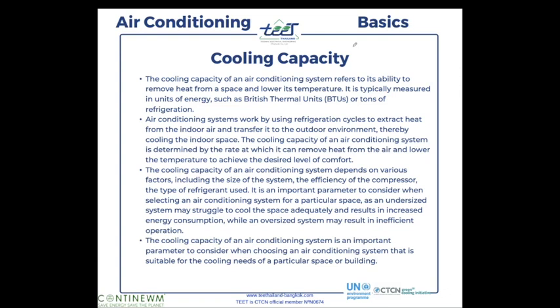But this would be only a guidance. What I am afraid of is that just because it's written on a slide, it's always working. No, we have to always look around. Let's take a supermarket with a good cooling capacity. You look and say, oh yeah, good, we have 5 air conditioners of 60,000 BTU, it's 300,000 BTU, the size is good. Perfect.